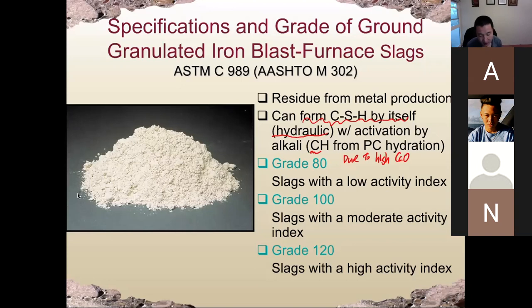Slag has different grades from grade 80 to grade 120. It depends on the so-called activity index. The activity index is defined as a ratio of two types of samples. One is a mortar sample with 50% of slag and 50% of cement.